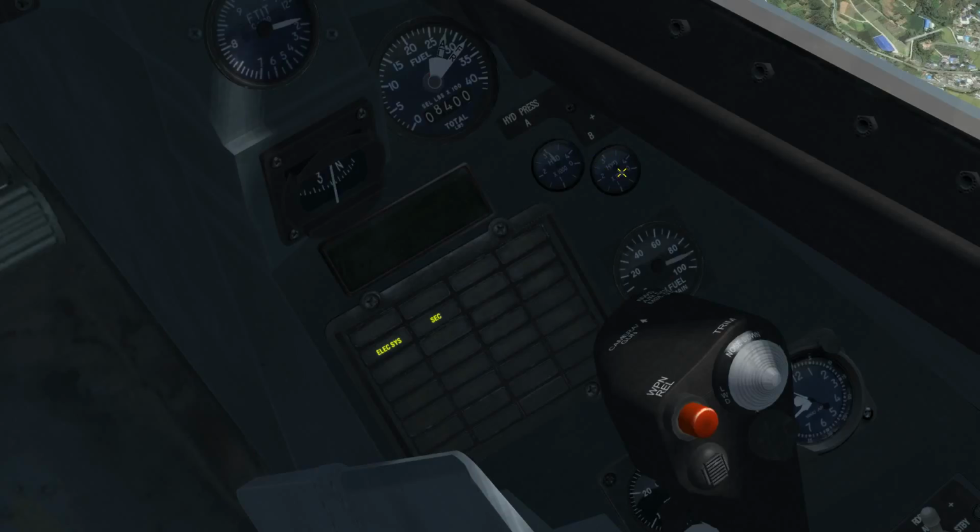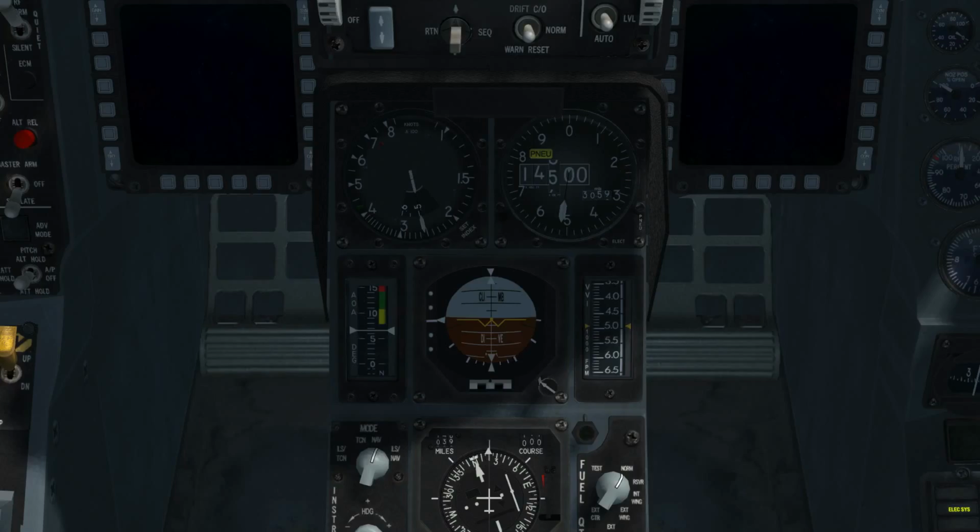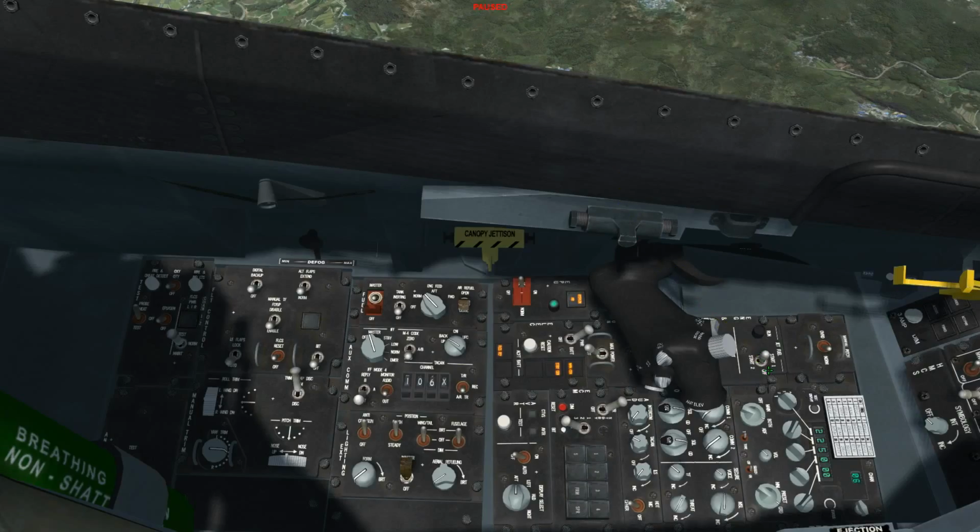You've lost the B hydraulic system, and it's the B hydraulic system that recharges the accumulators, the hydraulic accumulators that are used to get the JFS system to run. This is just a gas turbine, and it uses the same fuel that the airplane burns. And in order to get it to run, it uses accumulator pressure, and I guess that's to get the turbine up to speed so that you can introduce air and fuel and spark and get it to run continuously.